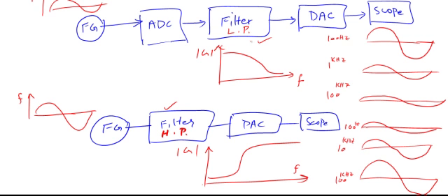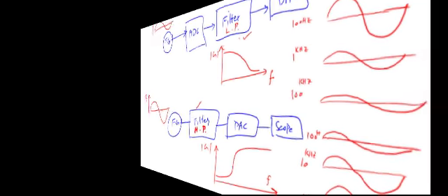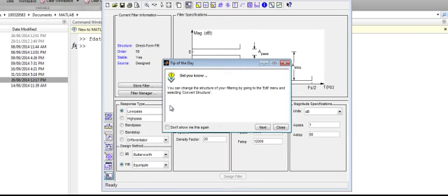filter is designed properly. So in this experiment you have to change the parameters of the filter to design low pass, high pass, and you design a variety of filters. You design Chebyshev, or you can design elliptic or Butterworth. So three types of filters you can design using FDA tool. I'm going to run FDA tool in MATLAB to show you how to input the parameters.